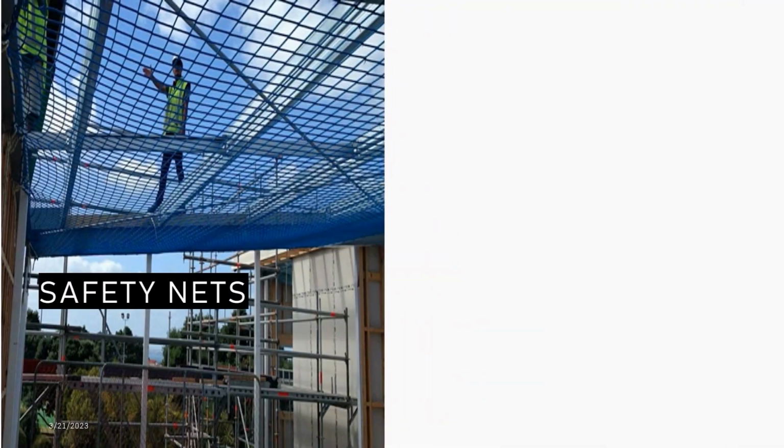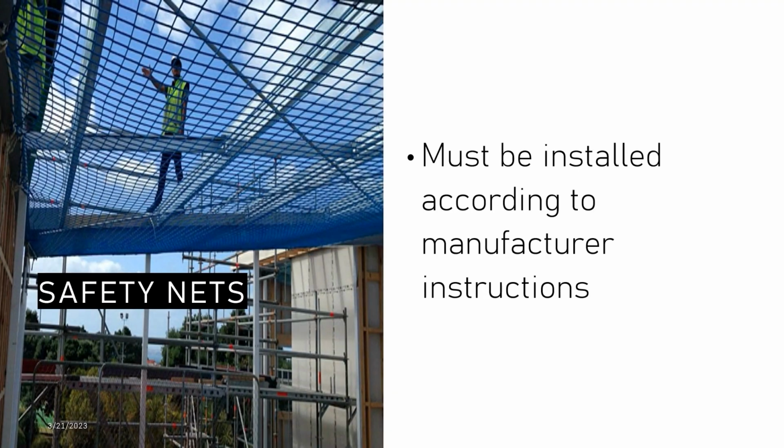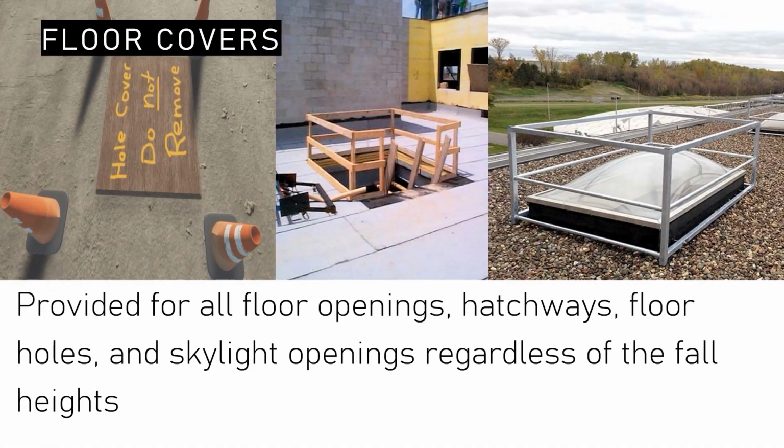Safety nets are good for high entryways and cathedral ceiling areas of residential homes. They must be installed according to the manufacturer's instructions. Floor covers need to be provided for all floor openings, hatchways, floor holes, and skylight openings regardless of the fall heights.